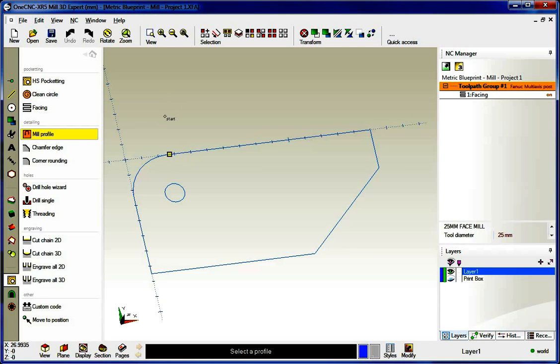I want to show you a couple things here. I just escaped out of the operation and reselected it. Notice that I can say I want to start here and terminate here. And as soon as I'm done picking, I right-hand mouse click, and then my cursor changes to the word start again. So I could come back over here and climb cut, and I want to terminate on that arc, and then right-hand mouse click. What that would do is it's more like a situation where your part's in a vise and you're just machining both ends there. So that's just another example of how you can select.